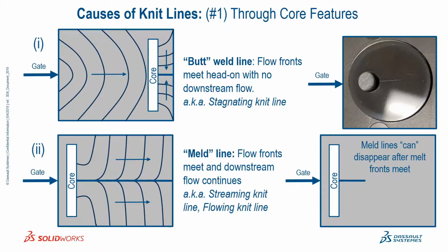The black part above that figure shows that exact situation where the part is gated. There's a round insert pin inserted into the mold, and material flows around that round pin and joins on the back side. You can see that the knit line only extends about 50% of the way to the end of flow. And that's oftentimes the case.